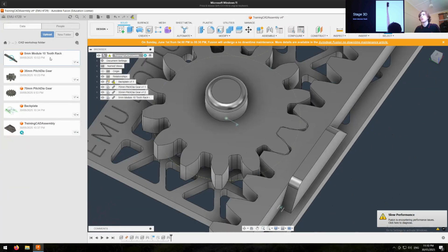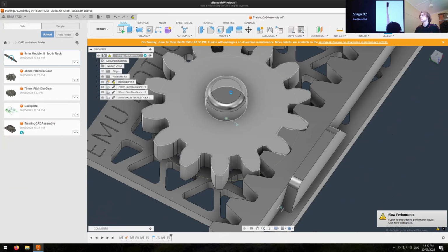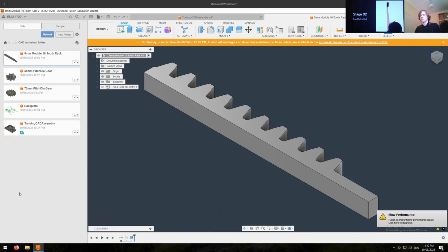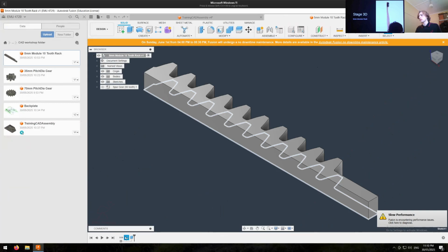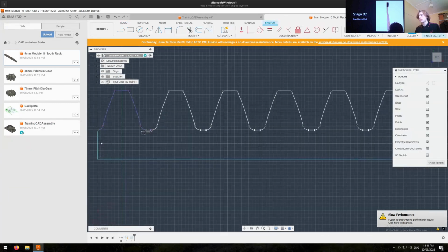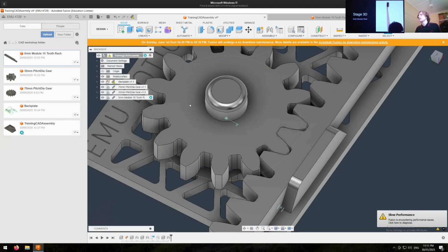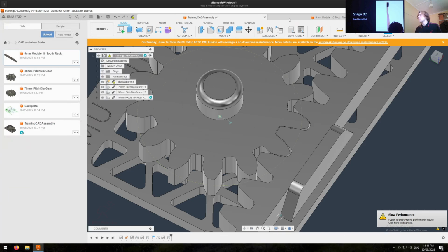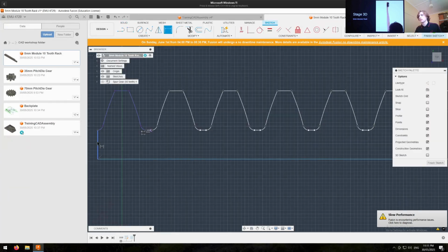So we're going to go and open our original file. And then we can go into our sketch by double clicking on it in the timeline. And we never actually defined how thick this is. So if we go in here, actually, I'm going to give this a thickness in here. So I'm going to define it. Let's say, okay, that's what it is now.